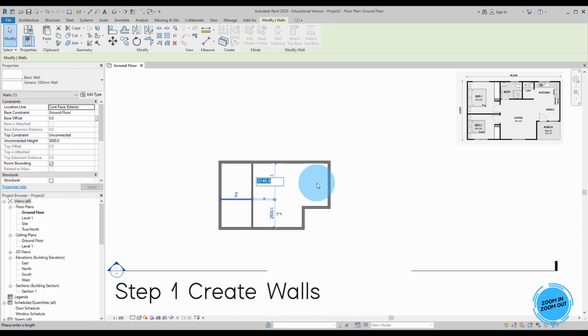So I can just click on here, and please observe what happens to this particular wall. 3400, it moves. And it just puts all the other things in place, and that's exactly what I want. So a lot of these things could be first roughly placed, and then you can come back to it and put it precisely.